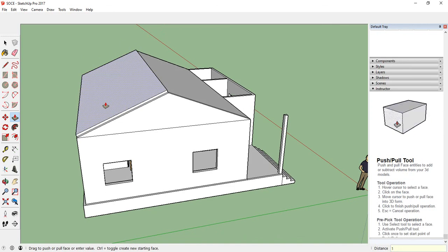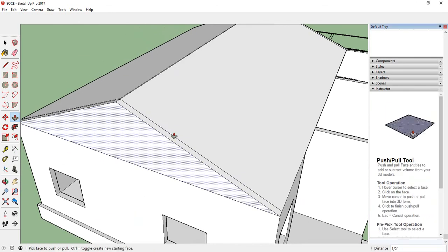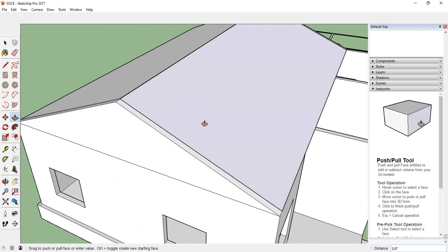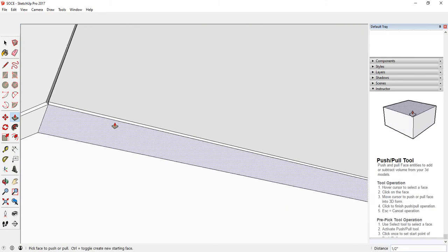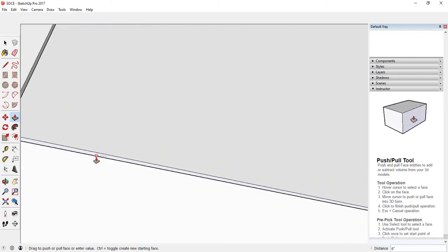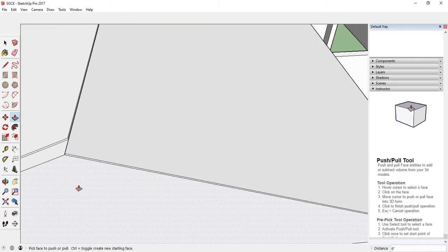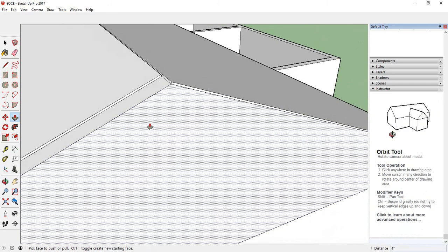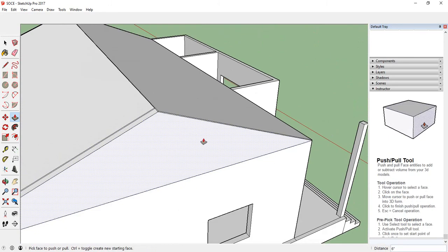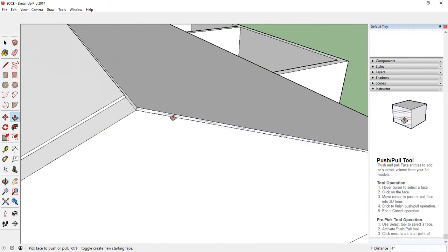Okay, I think it's enough. So, or 0.5 inch, 0.5 inch, then enter. And also that side, 0.5 inch, enter. Okay, so it's okay. And after that we can simply use the move tool, move that side with respect to that point, and here we can move that a little bit because we know that it's required.